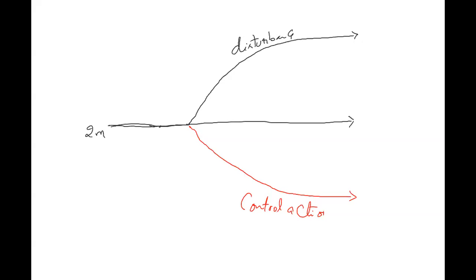Actual level. This is how my disturbance is going to affect my level. This is how my control action is going to affect my level. This has to be perfectly in sequence so that my level will never feel the effect of disturbance. Suppose if you take the control action a little early, also problem, because your level will decrease. If the control action is a little late, also problem. Your level will be affected. My objective of feed forward control is that the level should not be affected.